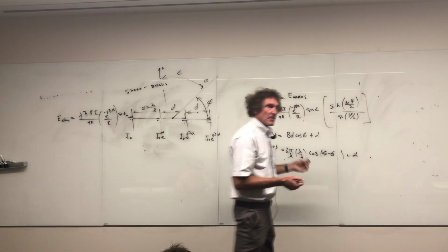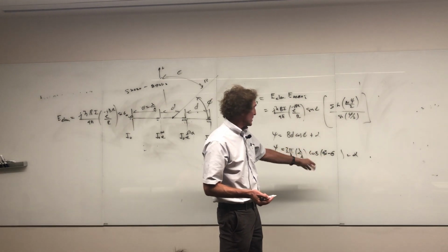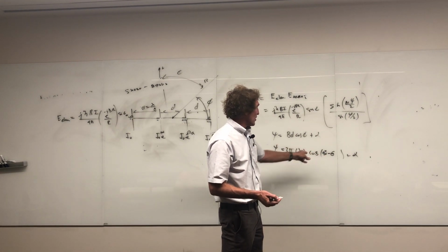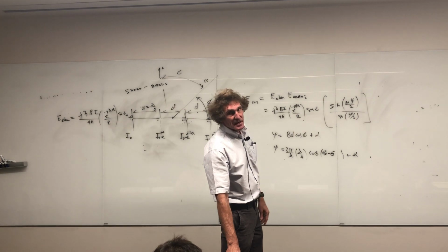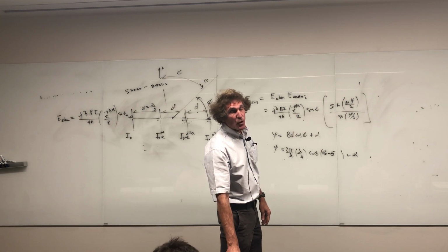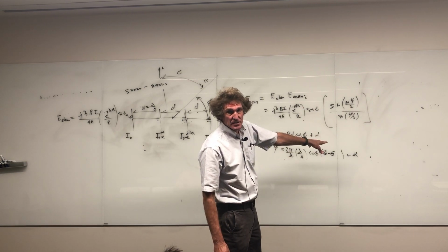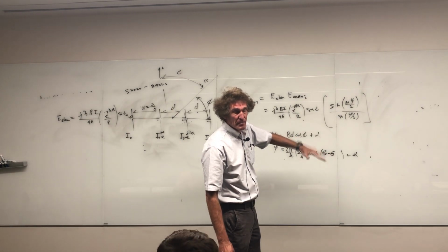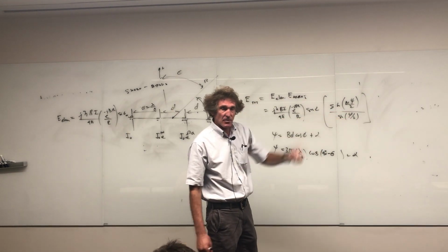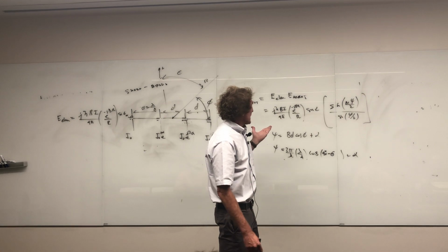And if you add alpha phase change here of 0, then it would just be this equation right there. By the way, cosine of 90 minus theta is equivalent to the sine of theta. If you want, you can do that. But I'm putting it in to make sure you see the angular variation. It's always the cosine of the angle r makes with respect to the direction of the array, the orientation of the array. That'll get you it.